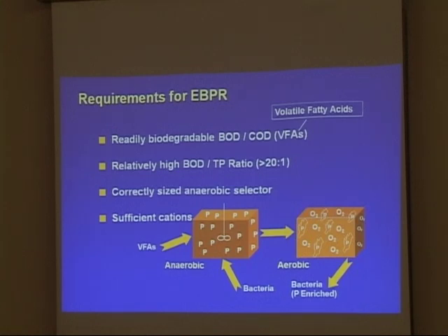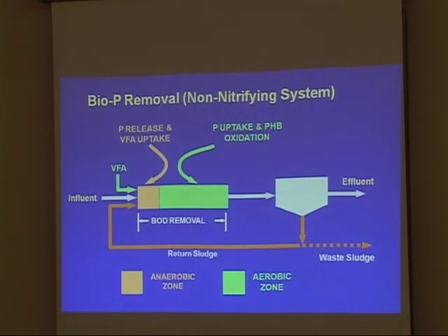The microorganisms have released phosphorus because they're stressed out in that first cell, or the first three, A, B, and C, those selectors. As it goes out into the aerobic zone, there's a lot of oxygen in there, and you'll notice the PAOs, the phosphorus-absorbing organisms, that's what those squiggly looking things are, have P locked into them now. They're pulling in the phosphorus. Your end result is bacteria coming out of there that are phosphorus enriched. Like I said, they have 125% not only of what was released, but of what came in the influent. So you've got fat P bugs.